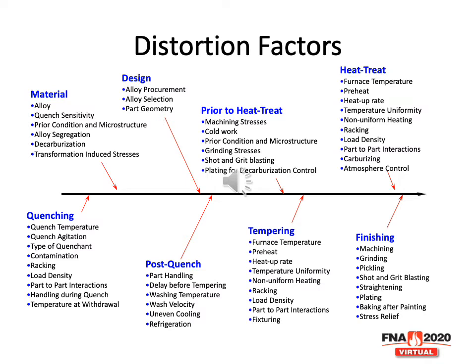Finishing operations also contribute to residual stresses. Pickling, plating, all those have a high residual stress associated with them and can cause problems during use and have, for instance, a shortened fatigue life. Grinding, obviously, will make a big difference in terms of the amount of residual stresses, particularly if you show up in your Wheaties and really grind it. You can develop quench cracks from the grinding operation or get local soft spots.